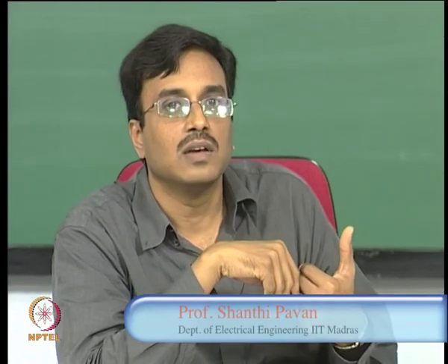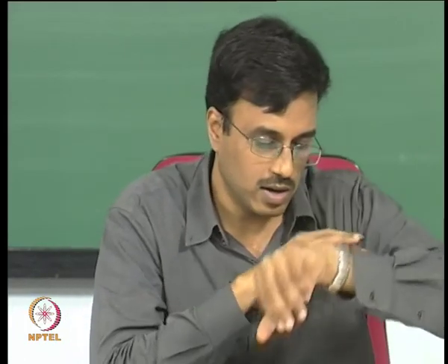So, in the next class we will see what we do to fix this problem and get (1 - z^-1) the whole cube as well as a good MSA. Because finally the problem is in the ω near π region. Correct, so we have to decrease the gain in that region. So, what does this do eventually? The whole modulator, what is it improving? It is going to increase the MSA. So, you can get the good noise shaping without losing too much on the MSA, right. So, we will see that in the next class.